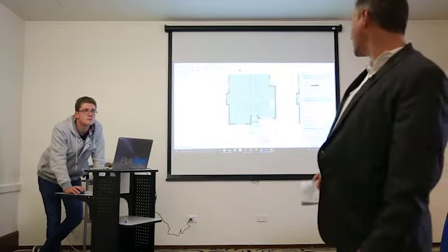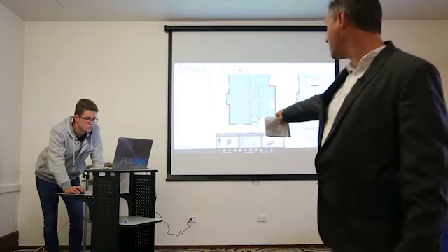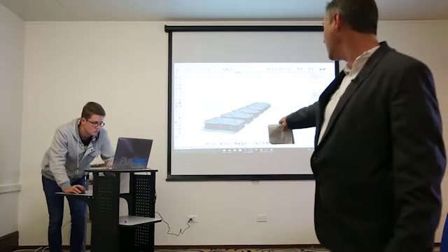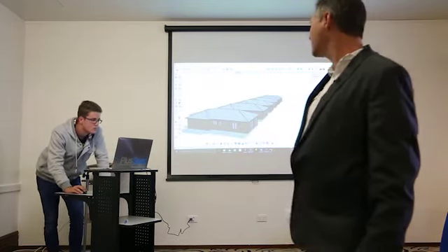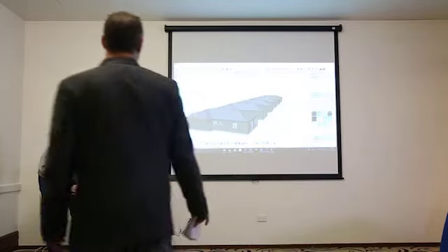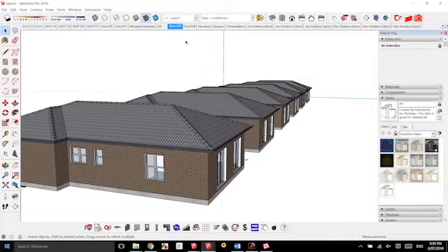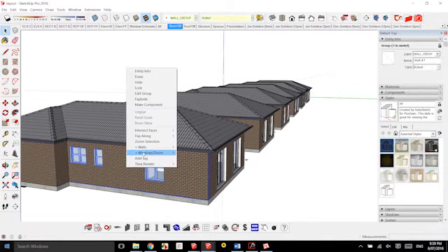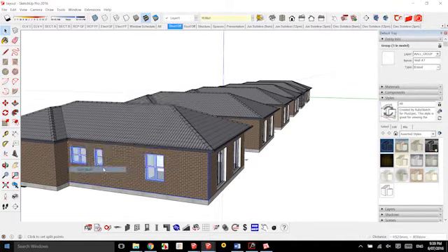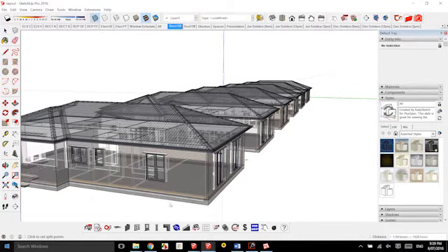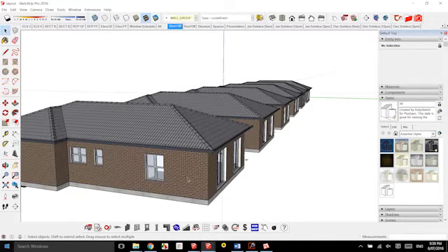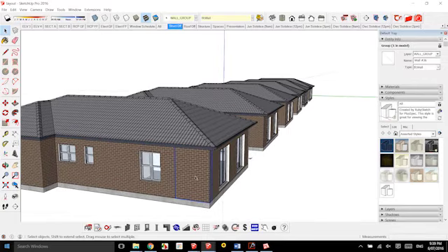Yes. Grant, do you want to go back to the model? Put a drop edge beam in, 600 long. Turn your shadows off so everyone can see, because the screen's a bit crappy, guys. Okay, so split that wall of the window, maybe the back 2 meters, roughly. That'll do. So we're going to split the wall there. There's two ways I could have done it. Maybe if you just go to the slab and put in a drop edge beam.